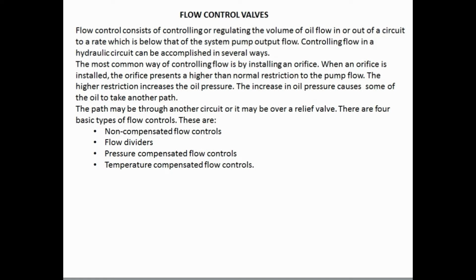Flow control valves. Flow control consists of controlling or regulating the volume of oil flow in or out of a circuit to a rate which is below that of the system pump output flow. Controlling flow in a hydraulic circuit can be accomplished in several ways. The most common way of controlling flow is by installing an orifice.